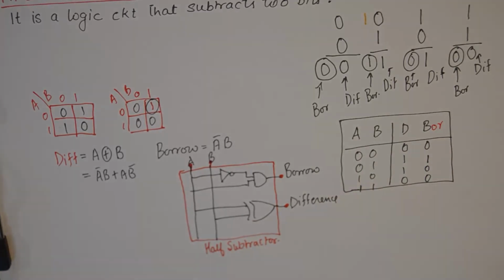So this is how simple the half subtractor is, and it'll be a building block of the full subtractor or the real life subtraction that is done on binary bits, because whenever subtraction takes place, the most likely case is a continuous string of bits being subtracted from a continuous string of bits, and in that case we'll be using full subtractor, and I'll discuss full subtractor as a separate logic circuit in the next tutorial.